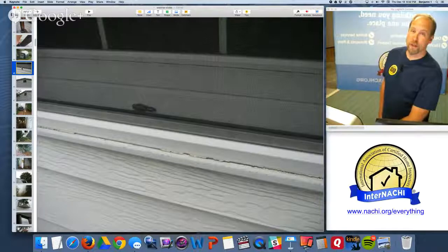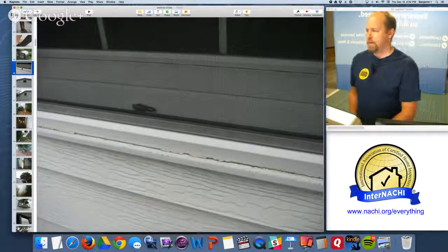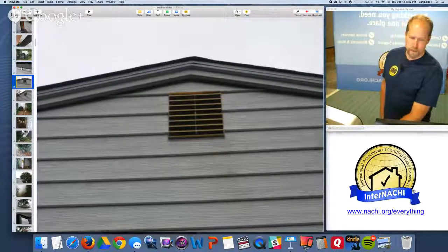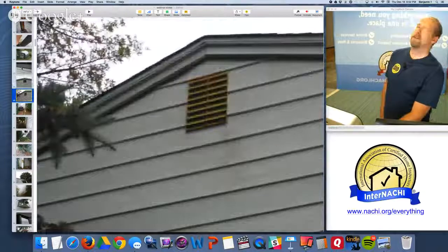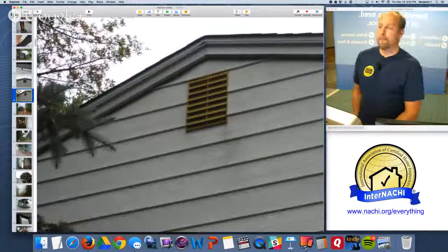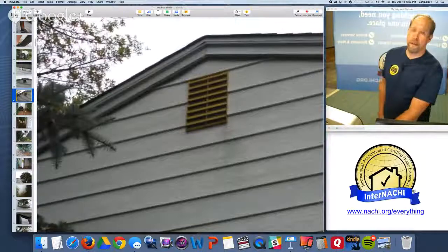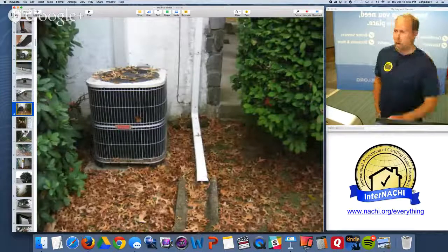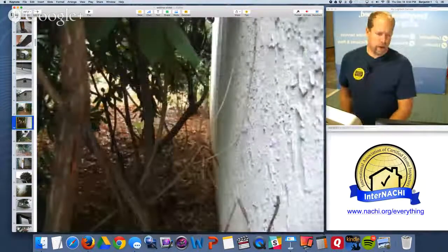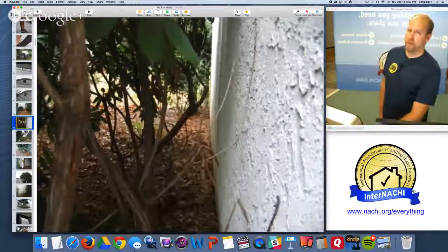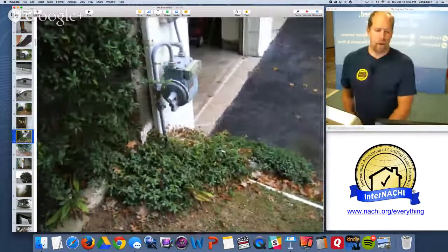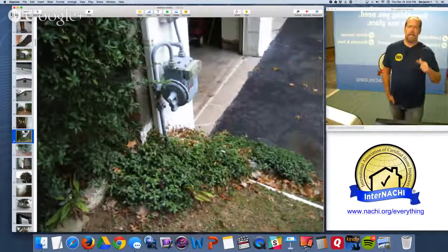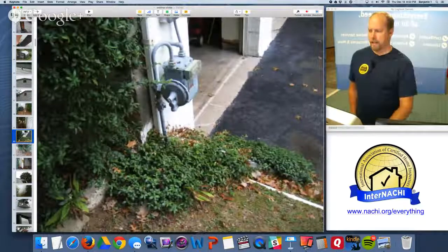The windows is a really great one. Second floor windows while I'm coming down. Really great opportunity to inspect the second floor windows when you're on the ladder. There's the gable vents. So now I have two gable vents, no ridge vent, possibly a powered roof fan, maybe soffits. Now I'm looking at downspouts. Downspouts should be diverting water far away from the house. We have a course on how to inspect for moisture intrusion. And one of the most common problems is moisture intrusion caused by improper gutter and downspout and splash block installations or maintenance.